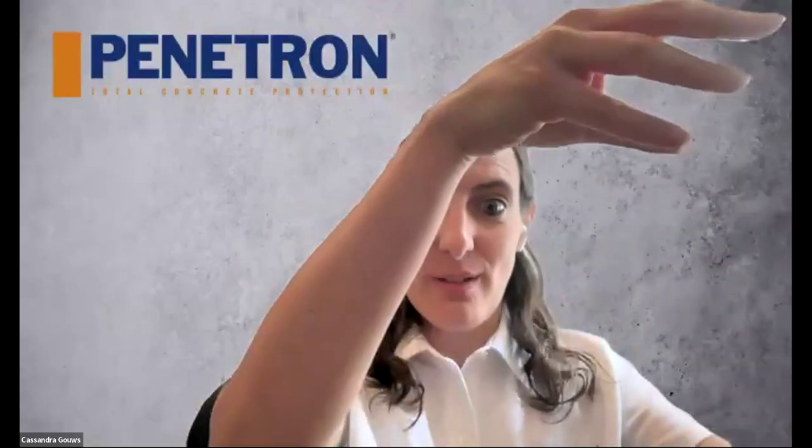then these two trucks you have to pour there, with the Penetron admix in it, and then have the non-treated ones on the inside. So it's not impossible, I've done it, but it is a logistical nightmare to be able to do it. So for the balcony applications, typically they opt to not go the crystalline route because they don't want to treat the entire slab.